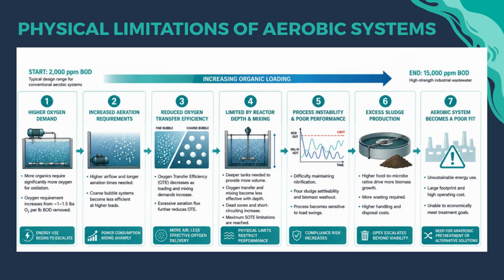above. As the strength of the wastewater continues to increase, we reach a point where the oxygen transfer efficiency begins to decrease rapidly under higher aeration rates, and this is really due to high bubble velocities and bubble coalescence, as well as reduced contact time and potential mixing limitations, and this is highlighted in series 3 above. As a result, these systems start to reach a practical and physical limitation.